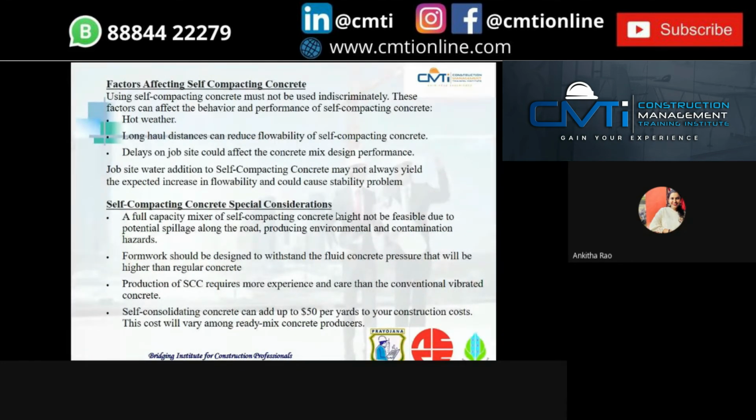The factors which affect the performance of the concrete are hot weather, long haul distance that can reduce the flowability of self-compacting concrete, and delays on job sites that could affect the concrete mix design performance. And the special considerations: a full capacity mix of self-compacting concrete might not be feasible due to potential spillage along the road, producing environmental and contamination hazards.